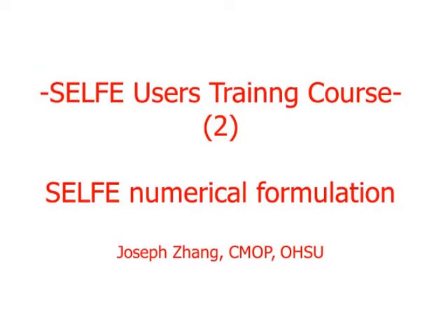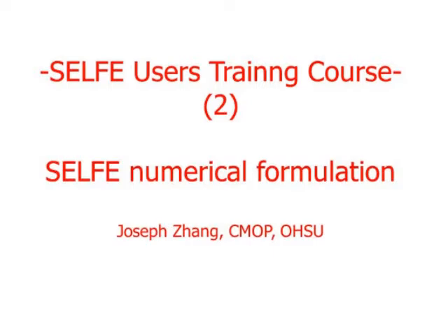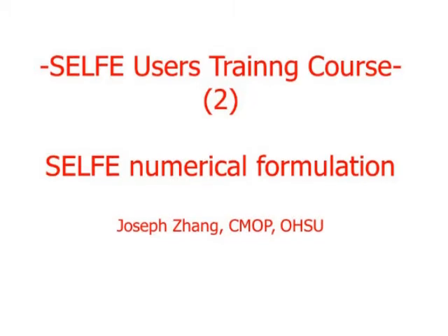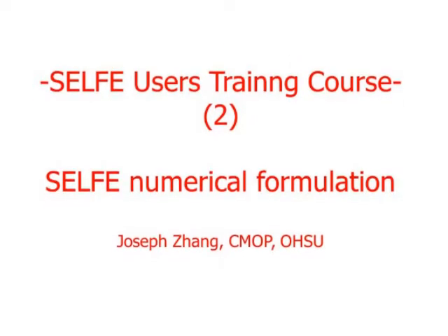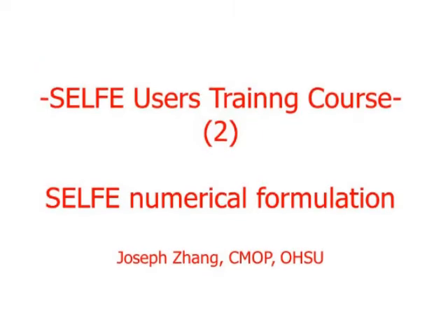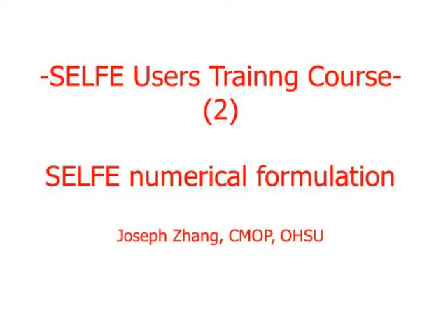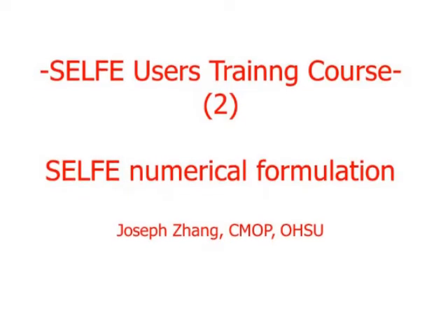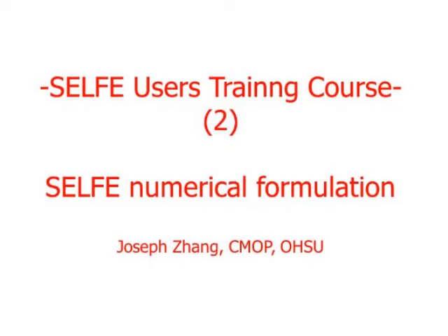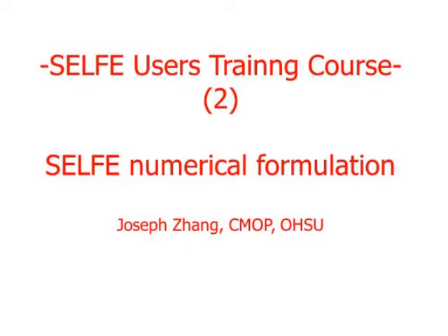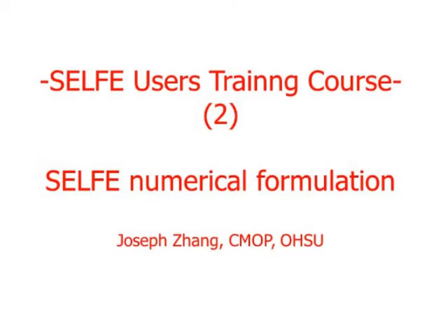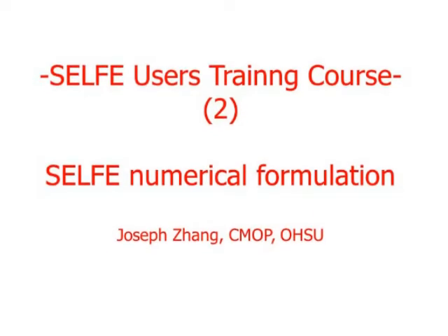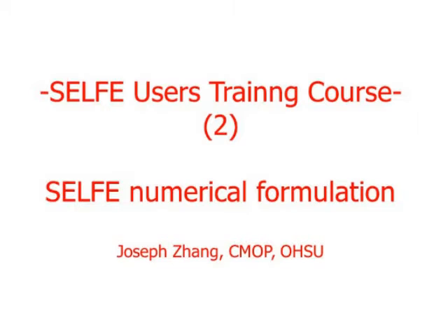Okay, so in the horizontal, we use this linear shape function, but this time we split each triangle into 4 sub-elements. Okay, the reason we do that is because the linear interpolation is diffusive. But then the diffusion is related to the element size. The smaller the element size is, the smaller the numerical diffusion is. So we want to reduce that numerical diffusion. So for that reason, we solve the transport equation at sides and nodes, okay, in order to do this kind of interpolation. And vertically, we use the cubic spline.